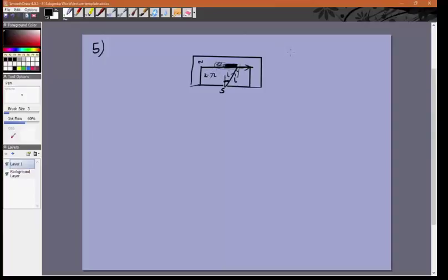And if this angle is I, what is tan I? It is 11.54 by 2, this is the radius, divided by this distance, the height, which is given to be 10 millimeters. Right. So tan I is equal to 11.54 by 20.